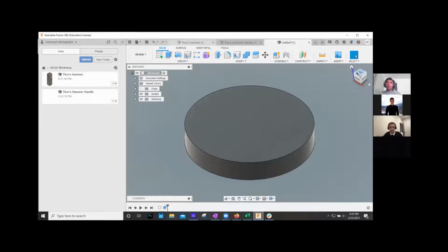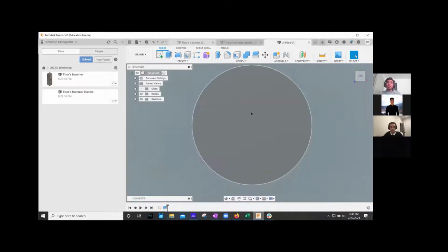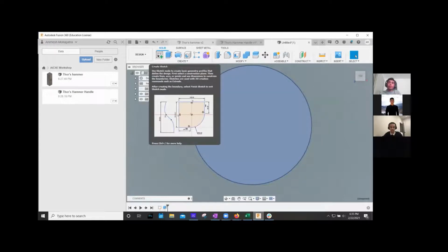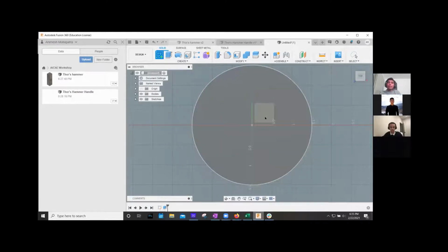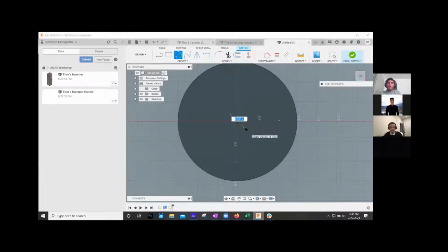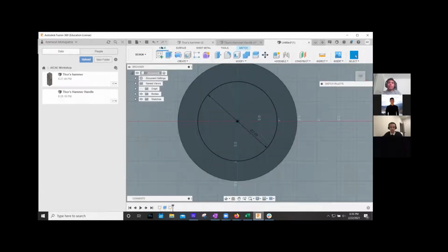So yeah, then go back to the top view. And this is now considered an object. So you can draw on this itself. And on this, I want to have a little circle puck thing rising out of it. I'll show you what I mean. So click on your blue face, like we did with the first hammer. And then click on this, and then click on your gray area. Good. And now I want another circle. And the diameter of this circle is going to be 2 inches. And I'm going to extrude this as well, so it sticks out.